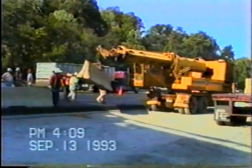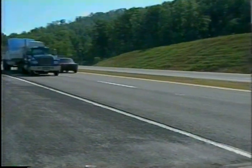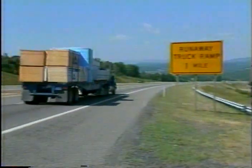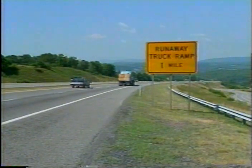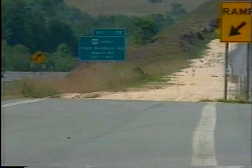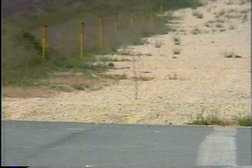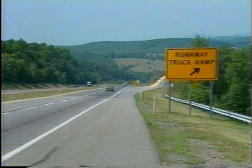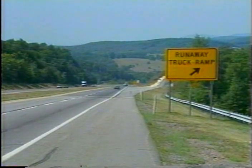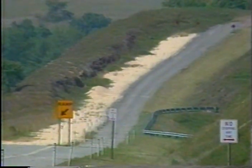There are a number of other devices that are worth brief mention. Runaway truck ramp signs inform truck drivers of all important ramps that can help them stop a runaway vehicle. These signs may have a supplemental panel telling what kind of surface the ramp has: sand, gravel, or paved. These signs are placed 1.6 and 0.8 kilometers from the ramp. At the ramp itself, there should be another sign discouraging other vehicles from entering.